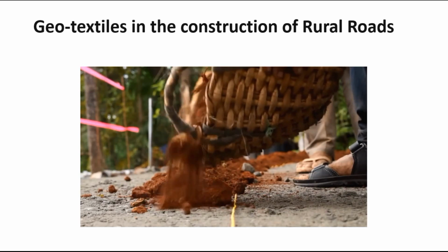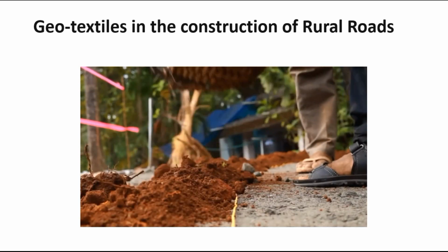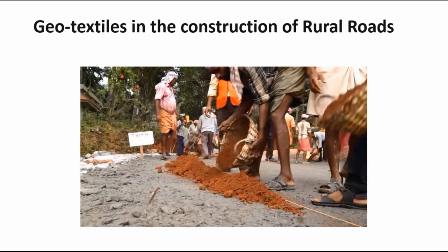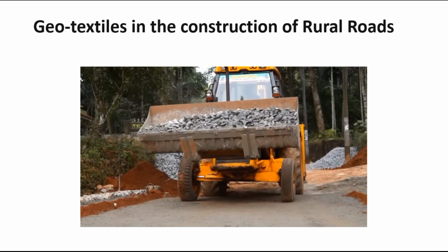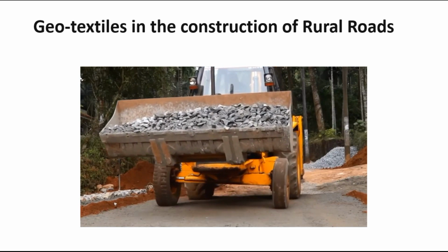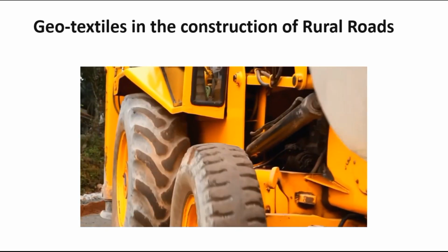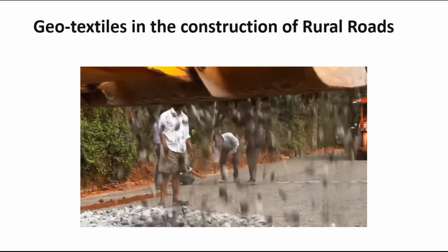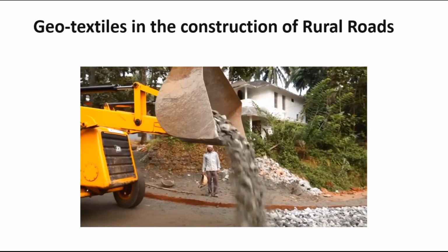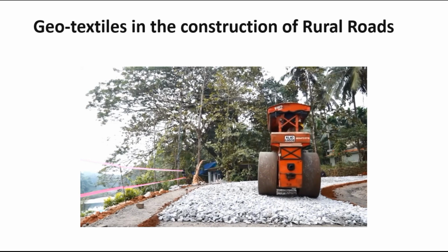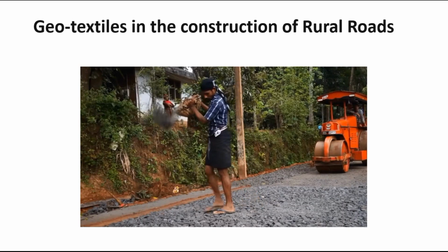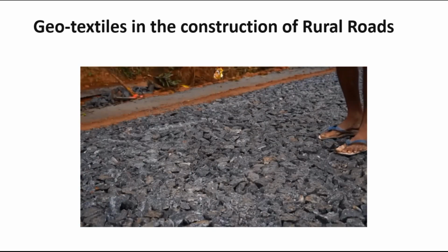After finishing the GSP layer, the shoulders are maintained with good gravel earth for spreading the grade 2 material as base layer, the width of which is 3.8 meters. This is dry rolled to the required compaction, and the screening material is applied to fill in the pores.